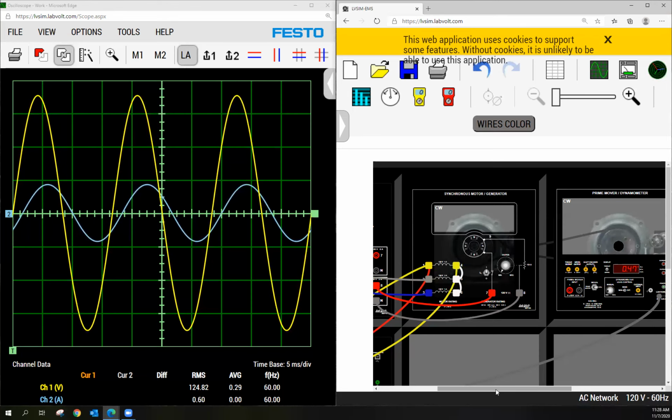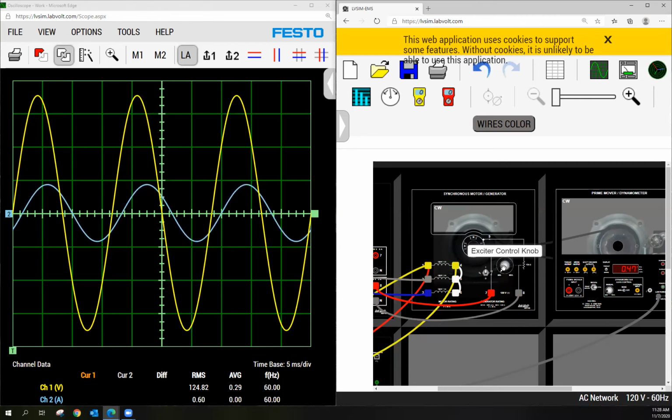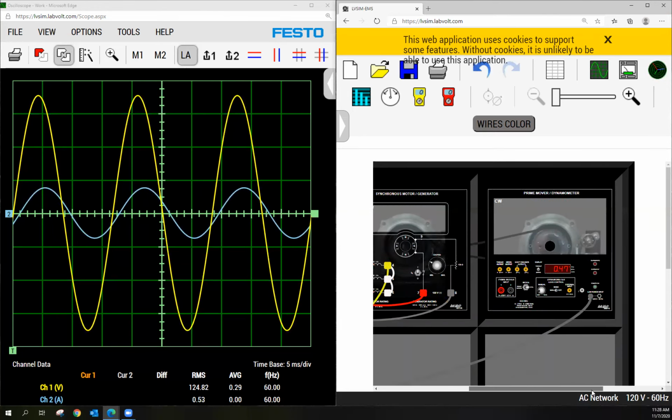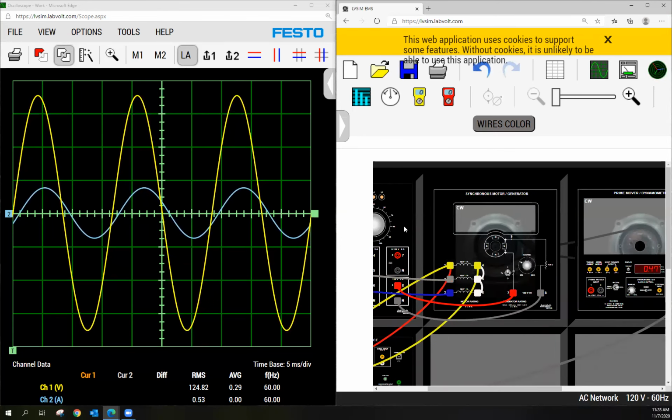So I hope this supports the whole idea of those V curves and the variable capacitive nature of this. You could even say variable inductive too, because you can make it lag differently as well, all with just the simple turn of this rheostat that controls the field current. I hope the theoretical and the practical concepts all came through in this lecture, and you learned something. Well, that's the end of the lecture, and I'll see you in class.